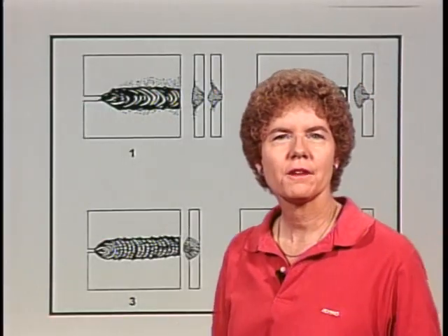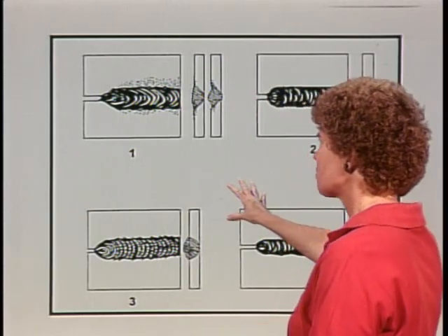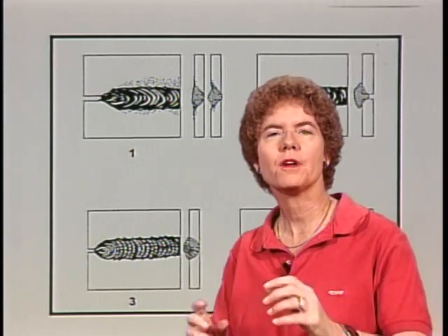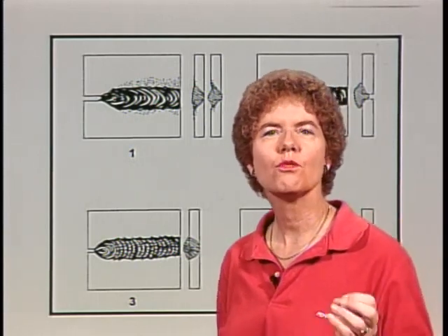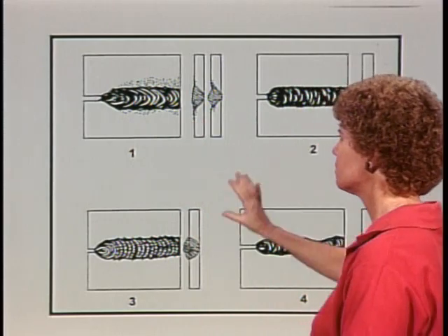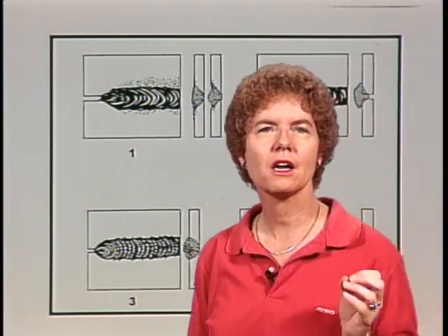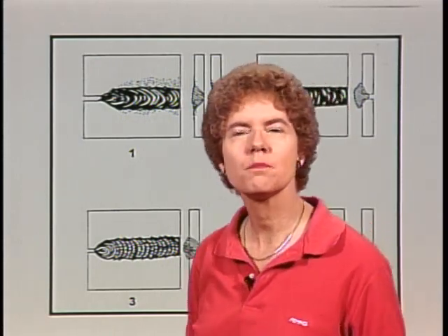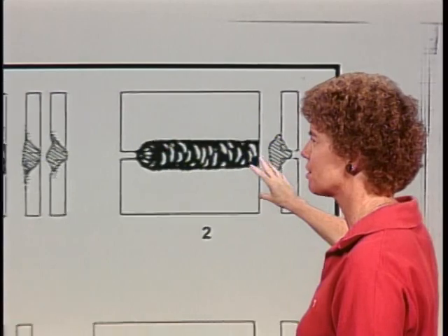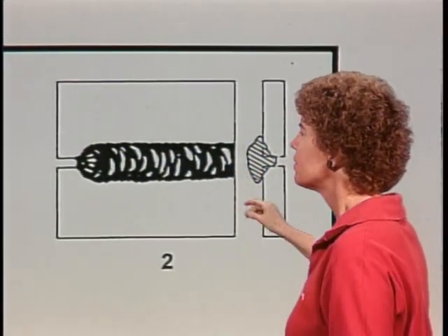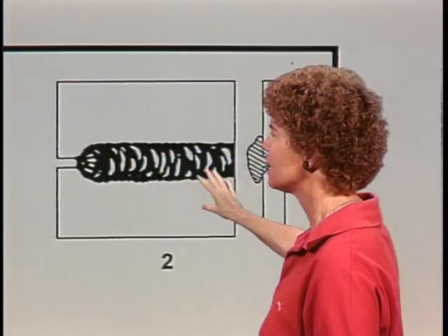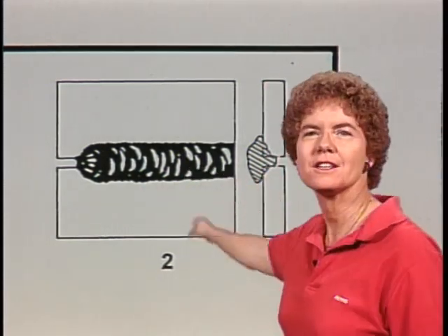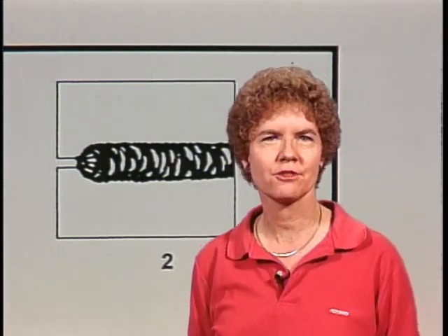Now take a look in the FAA figure pages at figure 44, which gives examples of 4 different types of welds. The FAA will give you this and ask you which one of these illustrations, 1, 2, 3, or 4, illustrates a cold weld. A cold weld is illustrated in number 2 in the upper right-hand corner here. With a cold weld, the weld will appear rough and irregular, and with the edges not feathered into the base metal. That's indicative of a cold weld in illustration 2.